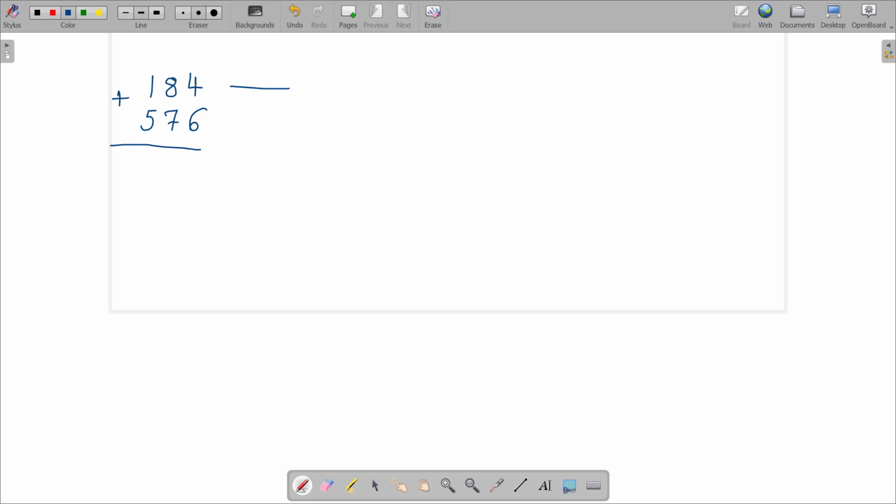So if I write the BCD code of the 184, I will have 0, 0, 0, 1 for the 1, 1, 0, 0, 0 for the 8, and for the 4 I have 0, 1, 0, 0.